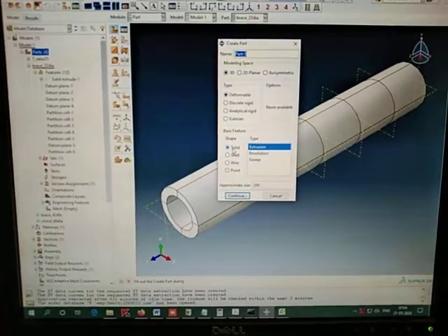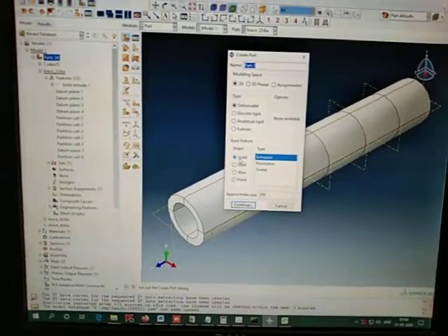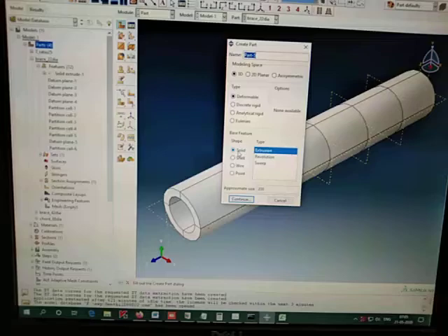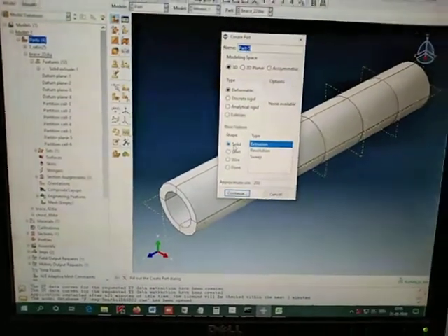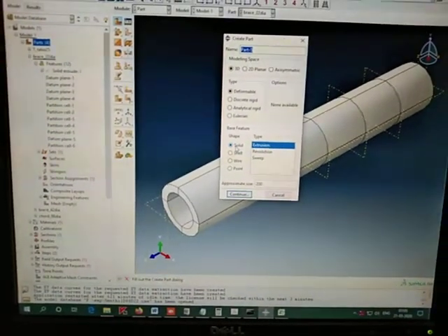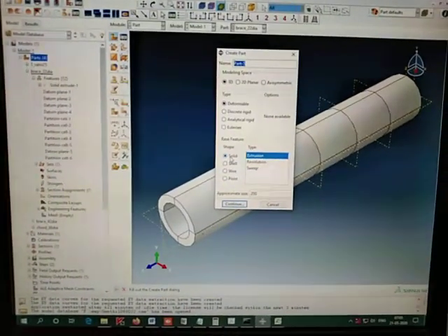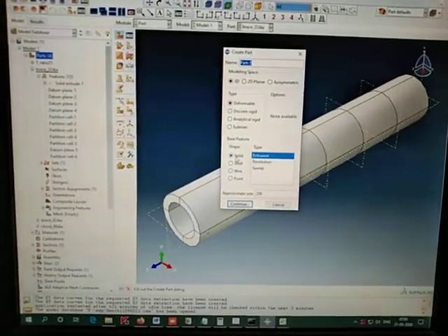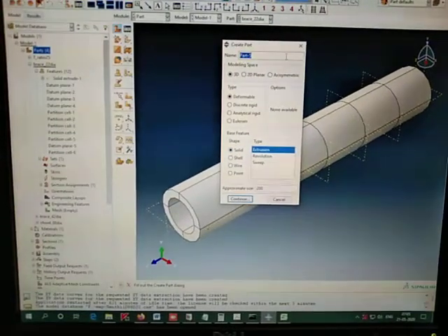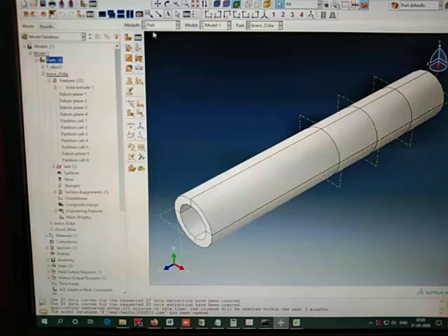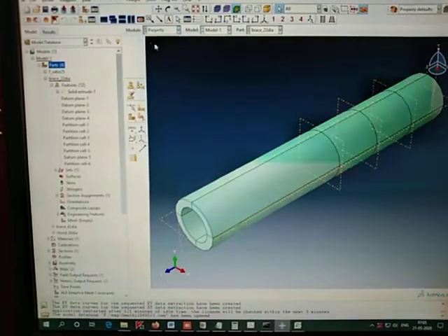Then for the type of structures, instead of solid you can opt for shell for analyzing tubular joints, where the thickness will be analyzed based on the shell. So the variations within the thickness cannot be analyzed, but exact approximate solutions can be obtained from shell elements. Then we can move further to property.